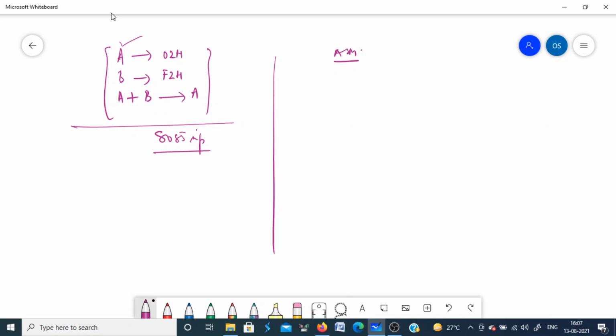I need an instruction which will copy data 02 into accumulator A. Okay, so I will look at the instruction set and find there is an instruction for that, called MVI, move immediate, A, 02. This instruction copies data into register A, whatever data you supply here. Suppose my data is 2, so I have written 2.